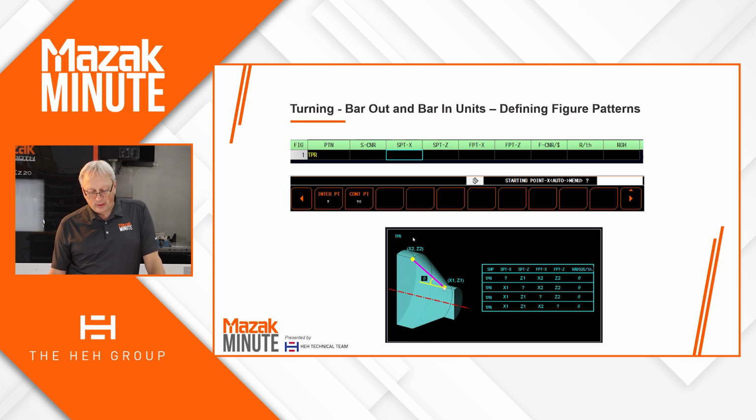The nice thing about the window down below, you're going to see the start point is going to be over here at the beginning or at the end of the straight line, and then you'll see the end point. It goes up to X2, Z2, and the chart to the right shows you where I can have a question mark in. If I have a question mark in one of those fields, we will have to put the angle under the radius theta column.